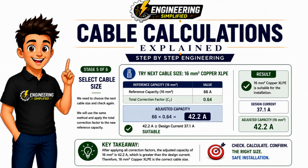At this stage of the design, the 16 square millimeter cable gives an adjusted current capacity of 42.2 amps, which is greater than our design current of 37.1 amps. So, based on current carrying capacity alone, the larger cable appears suitable. However, we're still not finished. Current capacity is only one part of the design process. In the next section, we'll continue by checking the voltage drop to make sure the cable also meets the installation requirements over its full 100-meter length.